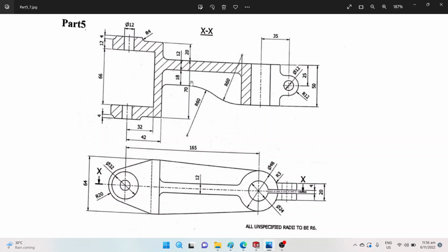Now, the reason why I do that is because the client or maybe your customer could come back to you and say, hey, I have an update on the drawing. This is no longer 70 millimeters, this is 100 millimeters. And that way it's easier to update your solid model simply by changing the dimensions, because your modeling dimensions match the design intent of the 2D.